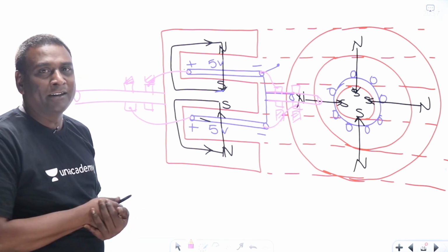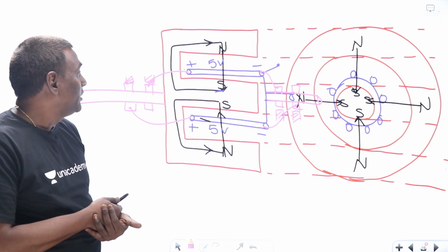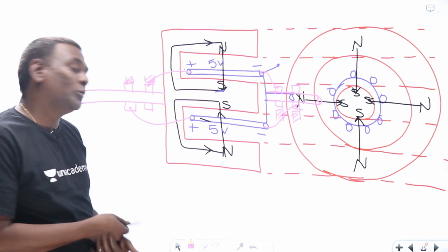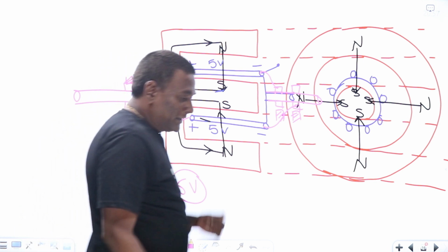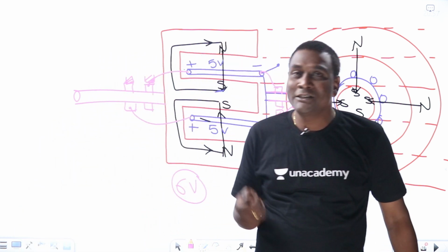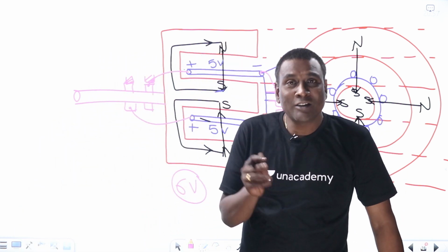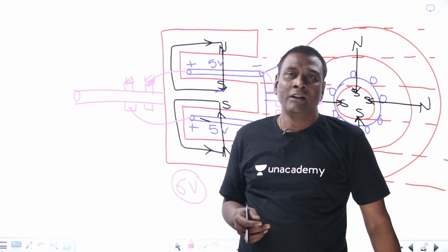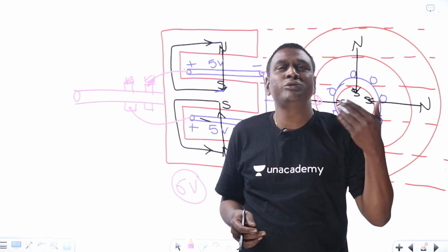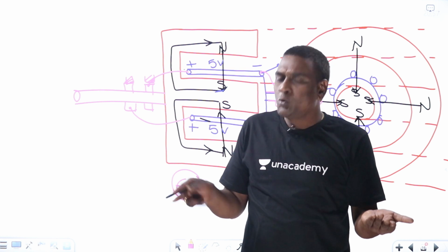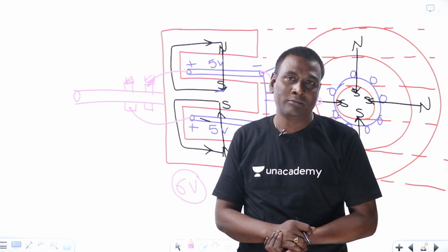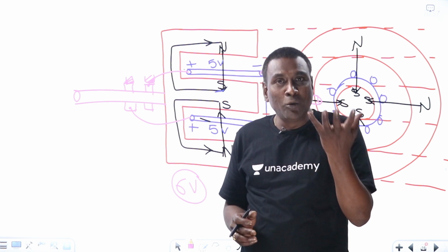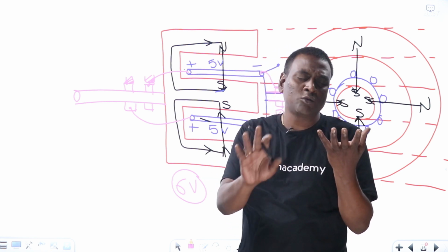Will I get 5 plus 5, 10? No. 5 plus 5 is 10 minus at least 4, it will be 6 volts, because in DC machines, brush contact drop will be there. For brush contact drop, you are going to deduct 1 volt. For example, in a DC generator, if it is producing 200 volts, with 2 brushes, 200 minus 2 is going to be 198 volts.